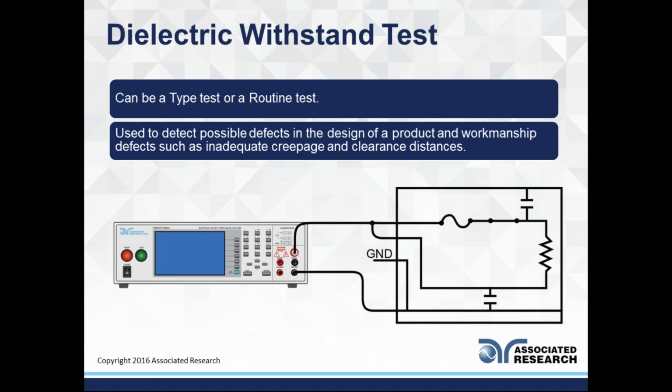So you've kind of simulated a capacitor, right? 2 plates holding a charge. So that's what these capacitors are. It's kind of just simulating what a Hipot test does to your line neutral and your ground circuit. So technically this capacitor here is everywhere, from all around this whole opening here, wherever that electric field is being exposed to between those 2 points. So this ground signifies that I'm shorted to ground here. My return is to ground.